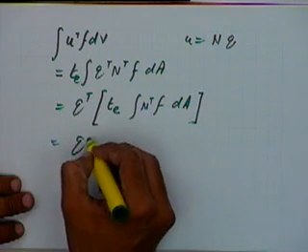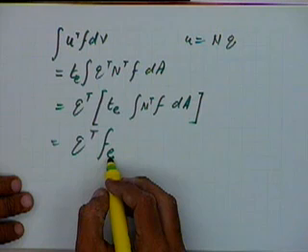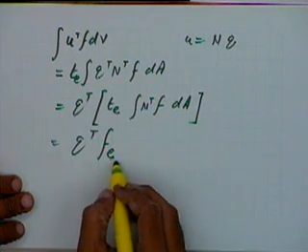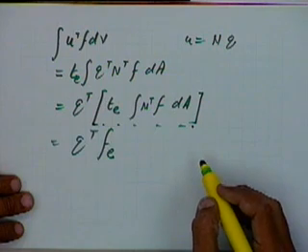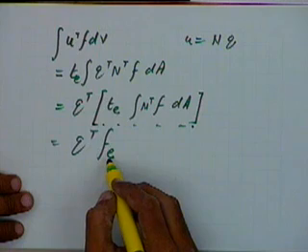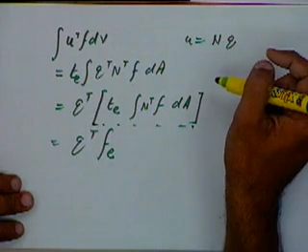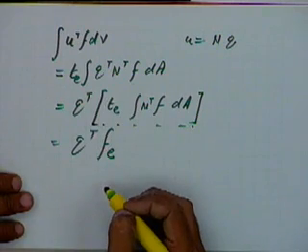So this is equal to, we will say, Q transpose into FE, where FE is the element body force vector. But again FE is computed only after carrying out this integral. Unless we carry out this integral, we cannot compute FE. So in the case of a 4-noded element, we have to compute this integral to find out the body forces, the effective body force acting at the 4 nodes.